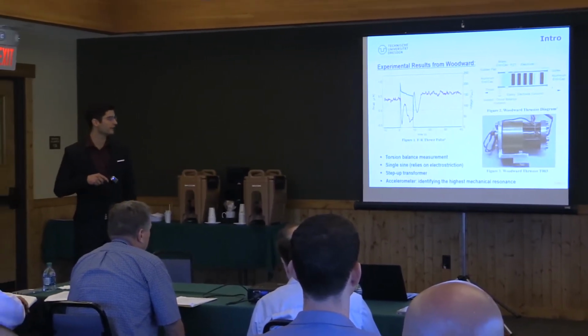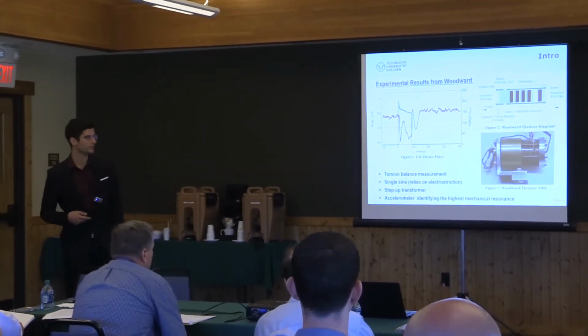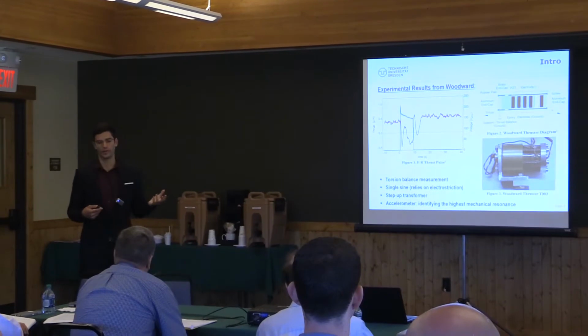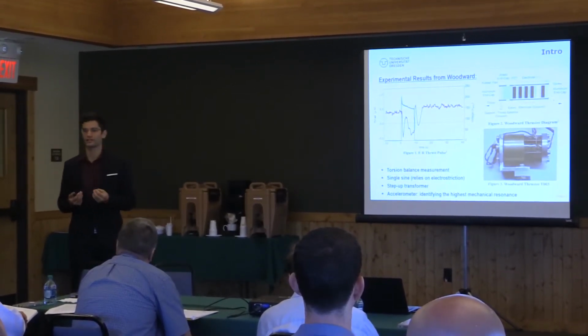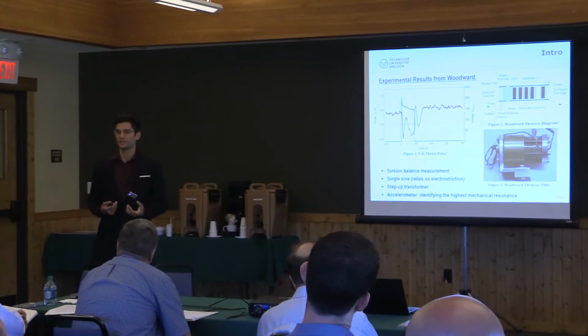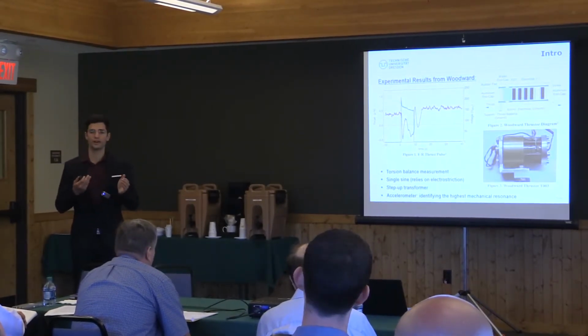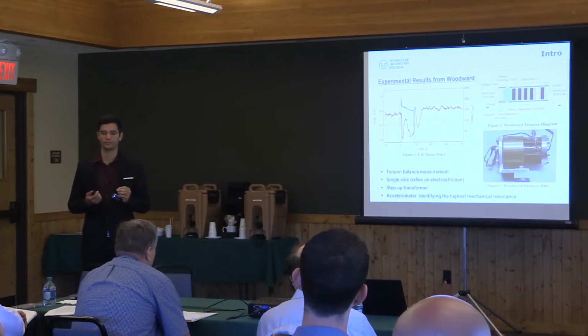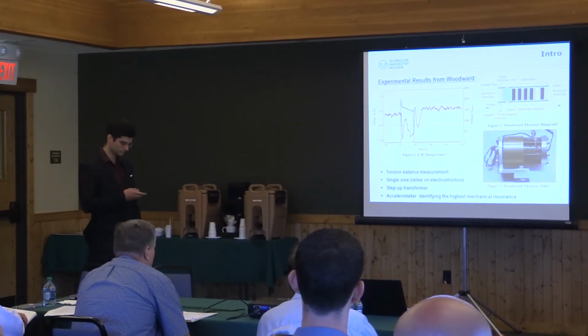Then you have the head mass, which is a lighter aluminum mass, which is supposed to be vibrating with a higher amplitude. In between you have the piezoelectric actuator, which is basically a multi-layer stacked actuator that provides the vibration, providing the extension when a voltage is applied through the inverse piezoelectric effect.